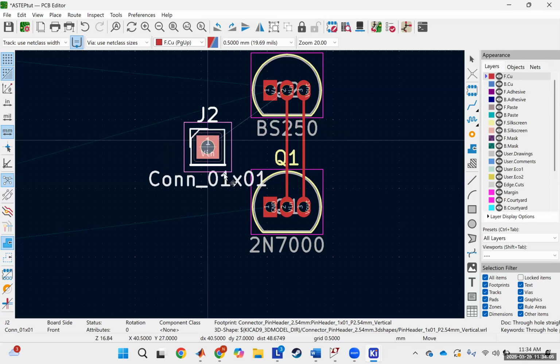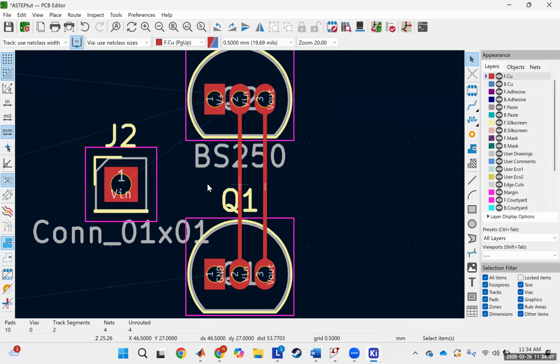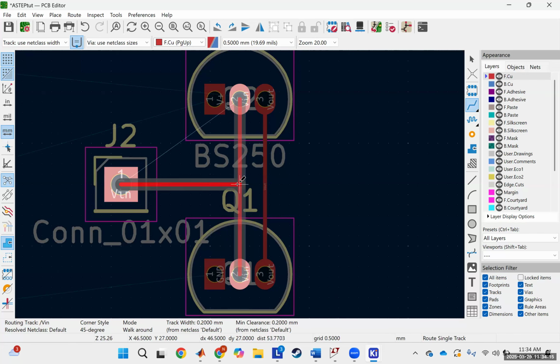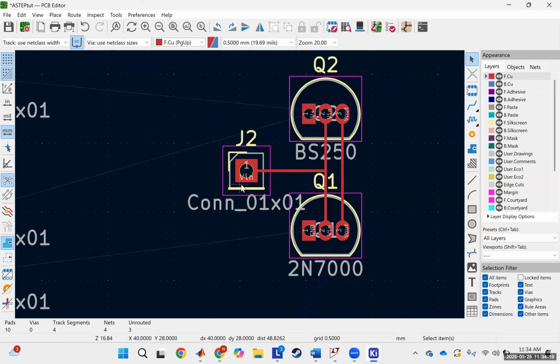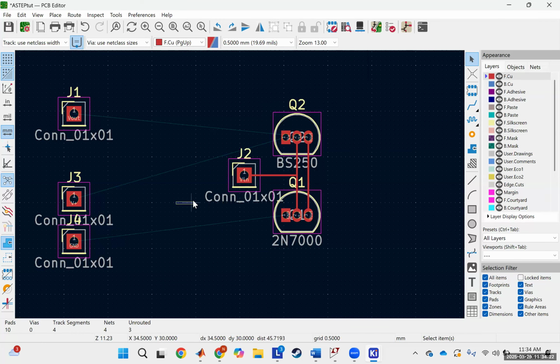Today, you'll put this on the same side, whichever one's closer. We know this VN is closer right here. We'll come back to our trace tool, click on VN, click here, and now you have that connected. As we connect these, you'll notice the blue lines start to go away. The blue line is really just showing you the shortest path to whatever node you want to get to.